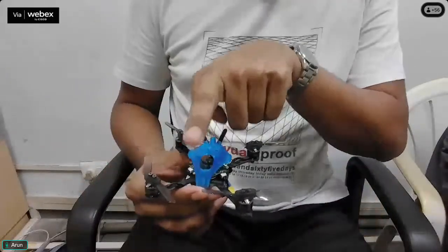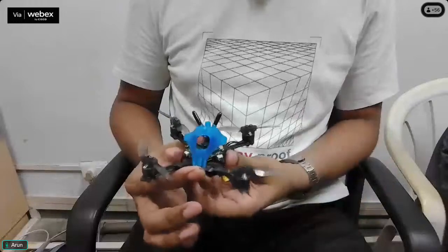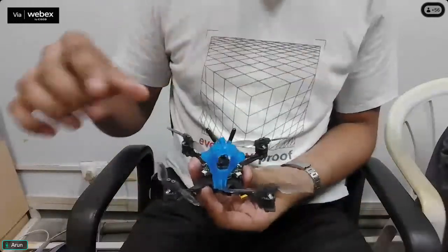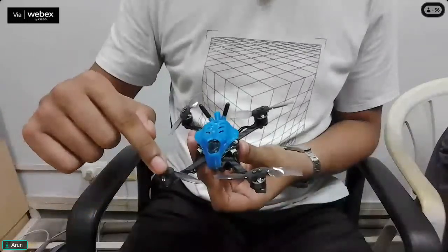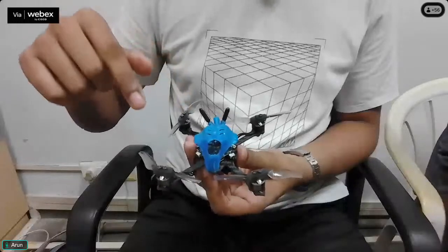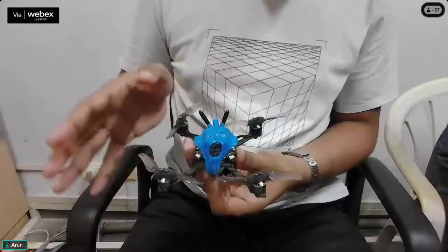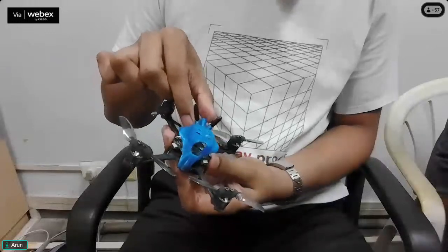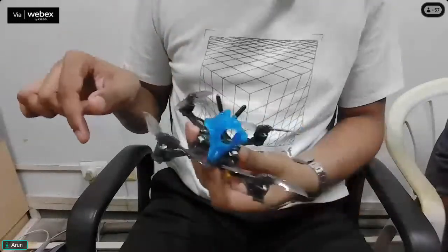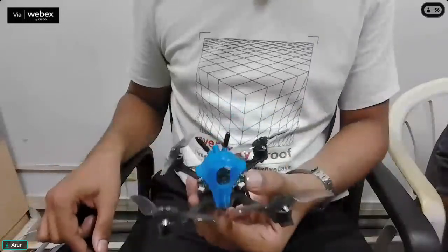And then for roll, this is, I can say, the x-axis. Let's say I have to roll to the left. What I do is increase the velocity of this rotor and this rotor. If I increase the velocity of these two compared to these two, it will create a torque in this direction, and the drone will tilt like this, and you can achieve roll motion. So this is pitch motion, and this is roll motion. Roll to either left or right, and pitch.